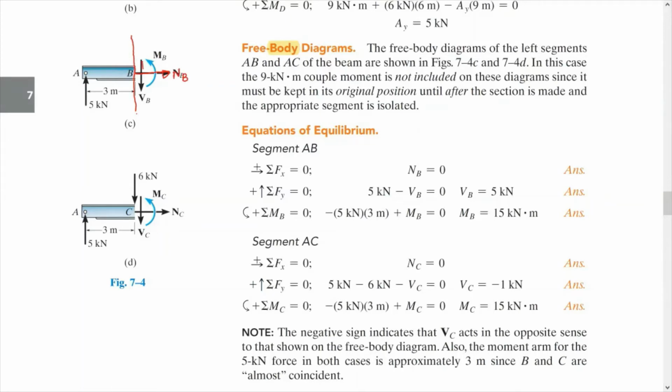positive as a tension here. This is shear force, positive if it's going to rotate the piece here clockwise. And here the bending moment is positive if it's going to bend the structural member piece and make it concave up. And once again, the sign convention is an arbitrary selection. You can choose whatever you want. You can choose the normal this way or that way, and the moment and shear as you like. But in the end, the final answers will tell you if your assumption is okay or the opposite. Okay? So here let's go with one sign convention. That's what I just showed you, okay?